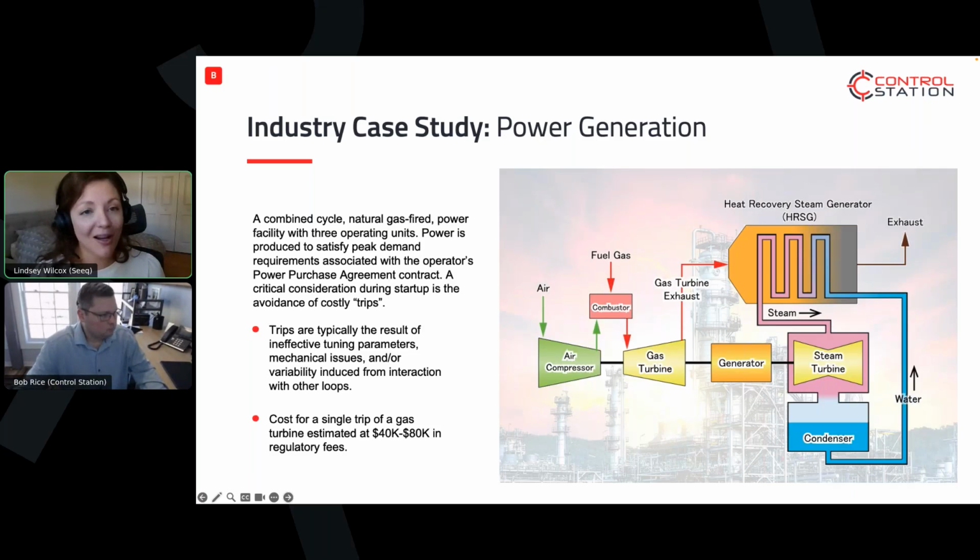And so I think it all comes down to, first step, let's identify those startup events, add the context to the data, of course, and characterize what looks good. So let's maybe start by overlaying those good startups, getting a visual representation of, okay, they all have the same shape, right? You can do more interesting things like building reference profiles of your signal.